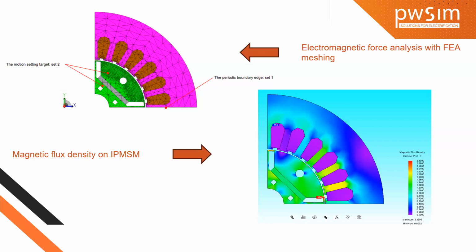So each and every part of your motor needs to be fine tuned. If it is not fine tuned, you can again see the error in the accuracy. Some of our customers are interested in improving the accuracy of their model, so at that time we can suggest that we need to improve the element sizing. So that's the thing, and this is with respect to the meshing and how our inductance is affecting our